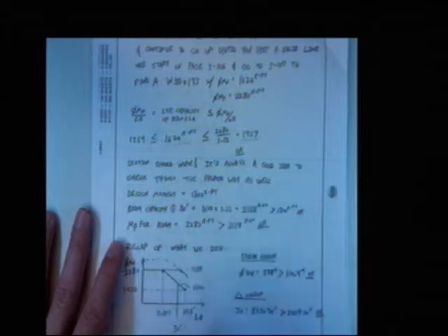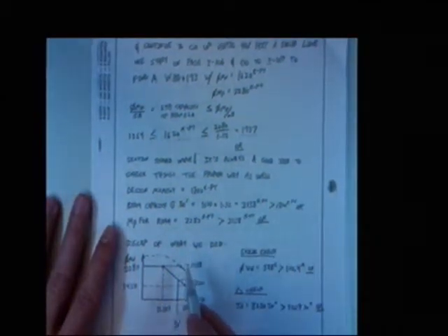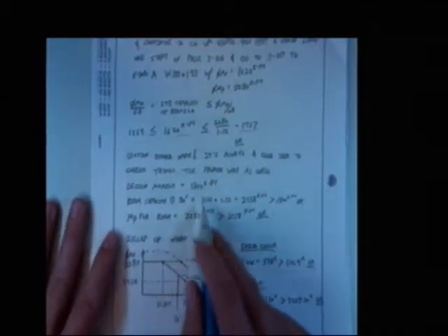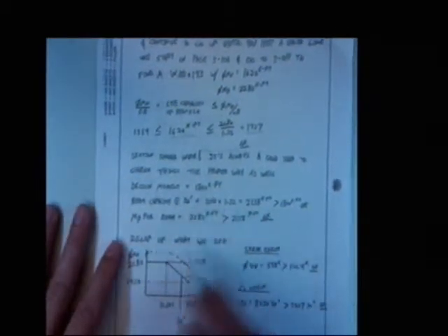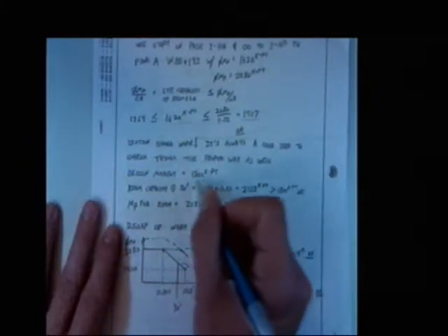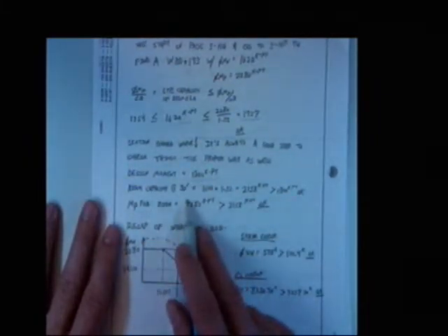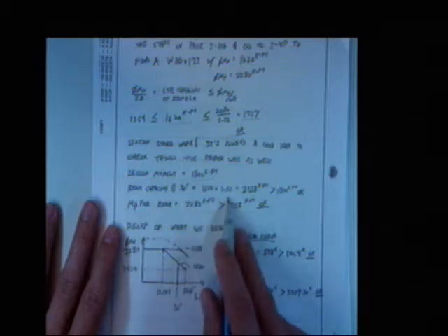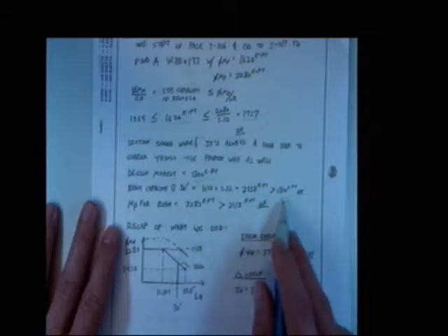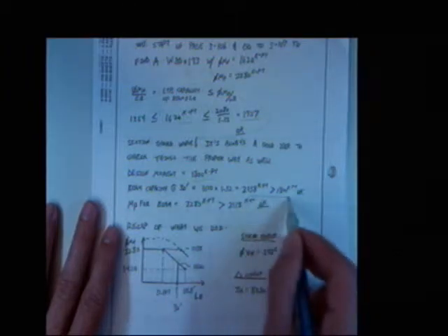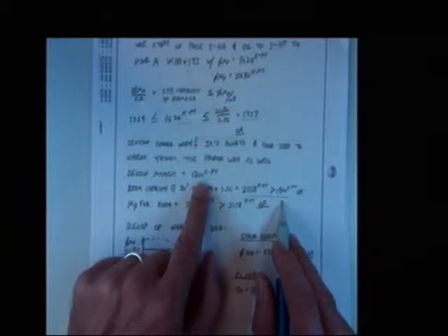Then I said it's always a good idea to check things another way as well. If this doesn't make sense to you, what I'm doing, you can always do the process like this. You can take your design moment of 1800 kip feet, take your beam capacity at 30 foot in length, and multiply by 1.32. That's my C sub B factor. I get 2138 kip feet, which is greater than 1800. That's good. That's making me feel good. 1800 is what my design moment is.